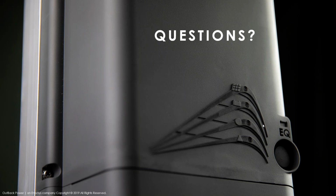The next question here is 7,000 watts divided by. Okay, so let's see. Let me read this real quick. So this is a question about nuisance tripping of an appropriately sized breaker. Right, this is a great question. So with the FM80, there was an issue that we had, and it still exists. So this is a current issue with the FM80, where when the PV array was oversized, so say an FM80 can only put out 80 amps. So if you put 5,000 watts or more than 5,000 watts of solar on an FM80, what could happen was when say there was some cloud edge effect or it was a cold day with a lot of sun, the amount of energy coming from the PV array to the FM80, some of it would actually exceed 80 amps.